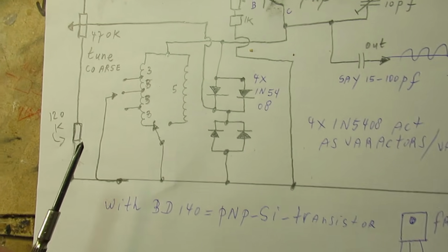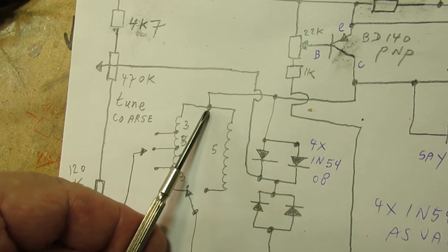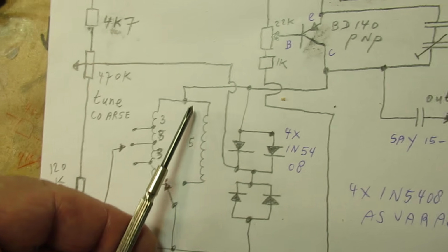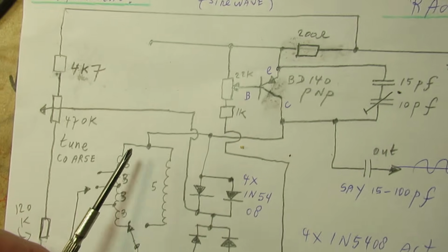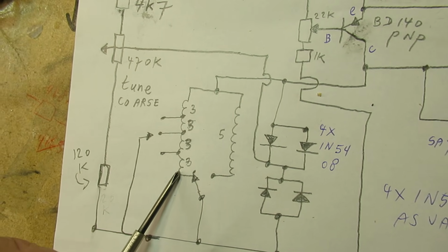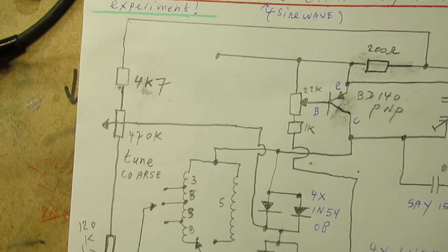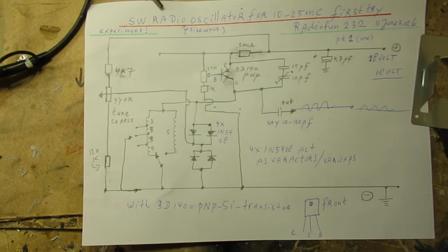And more important to tell, perhaps I need a very small capacitor here from the emitter of that transistor to the ground, in the order of 10 picofarad, to make the waveform more pure.